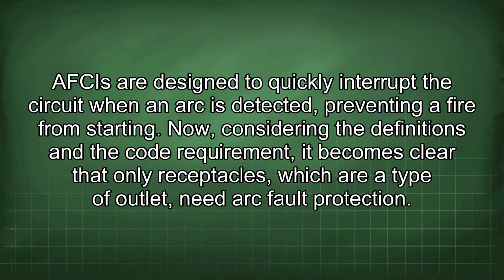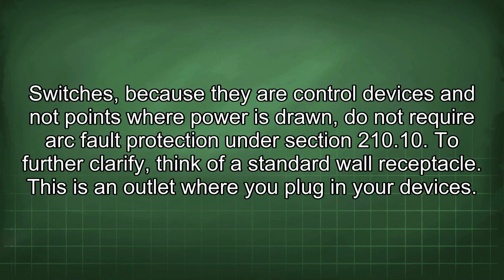Now, considering the definitions and the code requirement, it becomes clear that only receptacles, which are a type of outlet, need arc fault protection. Switches, because they are controlled devices and not points where power is drawn, do not require arc fault protection under Section 210.10.